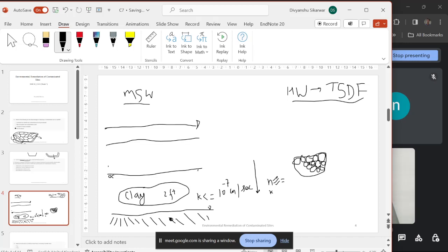In normal soil the water will get inside, in the case of clay also it will, and in the case of gravel also. But these spaces are called the voids. So porosity is the volume of voids divided by total volume. Total volume means the volume of this container. And permeability is how effortlessly water moves through the soil medium if we put water in it.